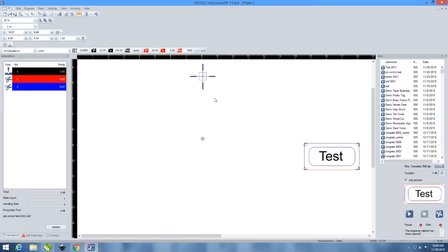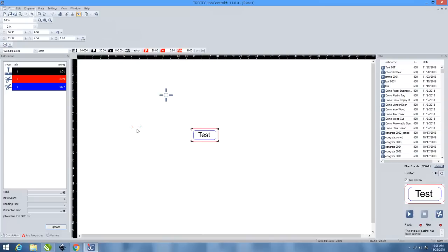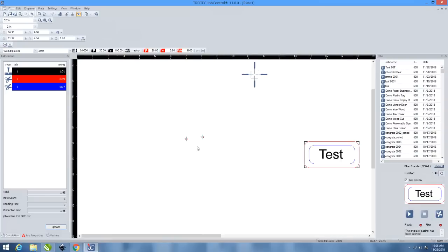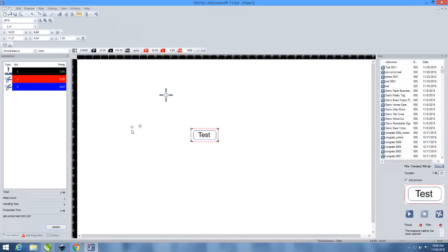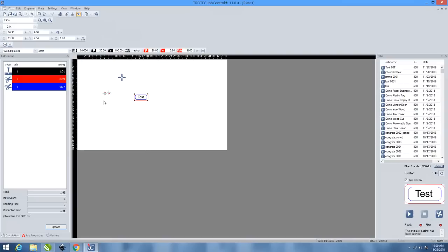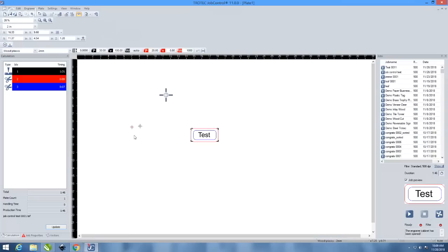And the marker is really great if you're doing jigs, and then you're switching the different nameplates, like you're switching the different jobs of the jig. You can put markers where the actual cutouts of the jigs are, and then you can save that job, like the job control file. You can save it, and then when you switch jigs, you can just open that file already ready to go. So that's why markers are nice. That's a great option. You could do the same in your design file. This just gives you a little more freedom in job control.